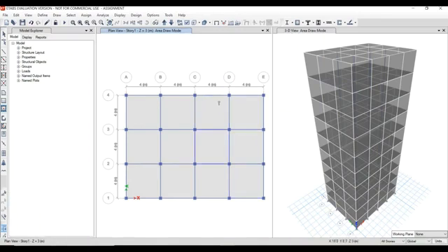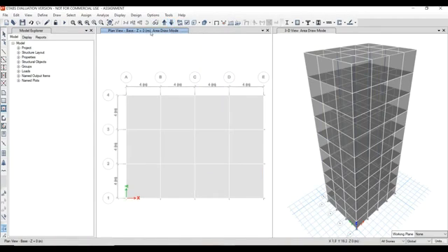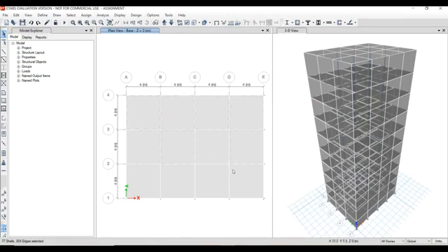And now we need to assign the loads. Before assigning the loads, we need to make sure that the base is a fixed base. To give the fixed base, go to base, plan view, z equals 0. In that place, we have the slab floors, which are already assigned due to selection of all stories. Now select the individual stories. Click this one, click escape, and now select every panel.